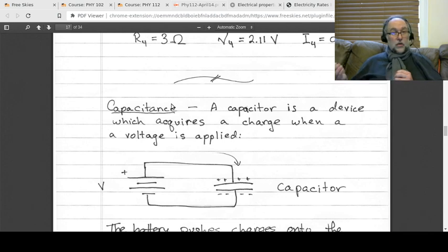The current is the flow. That's how much charge is flowing per time. The resistance is what limits that flow. And now we have another concept, another electronic property, and that's capacitance. Okay. Now, what happens when current flows is I told you a minute ago that whatever flows into a component has to also flow out of the component, otherwise charge is building up. Can charge build up? Yes, only temporarily though.